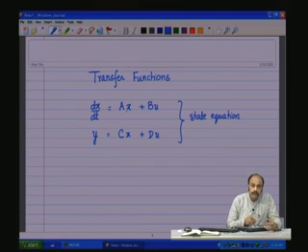What is going to differ from system to system, circuit to circuit, is the A matrix, which is the parameter matrix for the system, which defines the characteristics of the particular circuit, the B matrix or the input scaling matrix, the C matrix, which is the output scaling matrix, and the D matrix or the feed forward matrix. This is the output equation, and the first one is the dynamic equation.